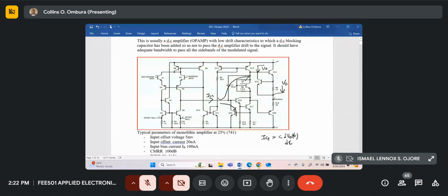The AC voltage, of course, the bias voltage for proper operation of the circuit, the base of Q14 should be slightly higher than the emitter of Q14 for biasing purposes, maybe 0.5 volts between the two. But the AC varying, because the voltage gain of the output stage, which is an emitter follower, is just maybe 0.99 something.